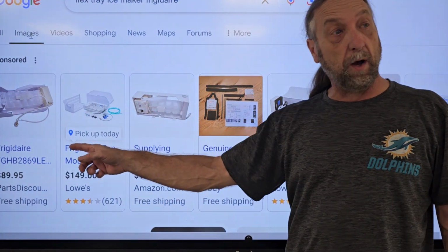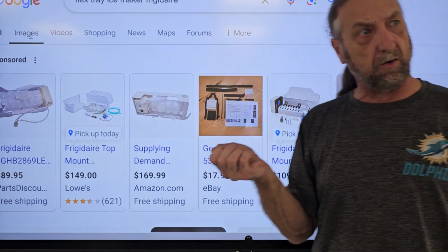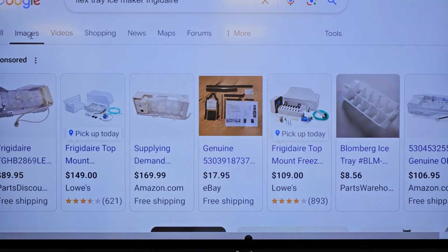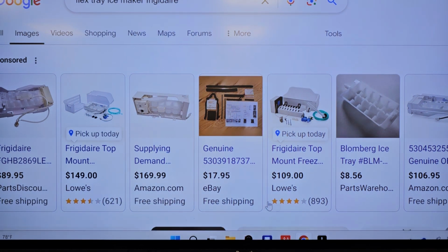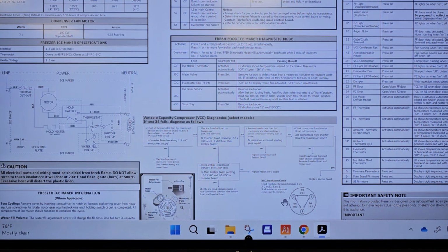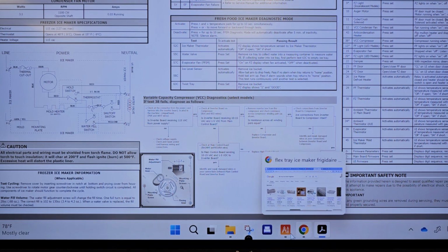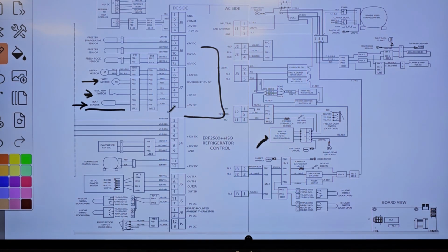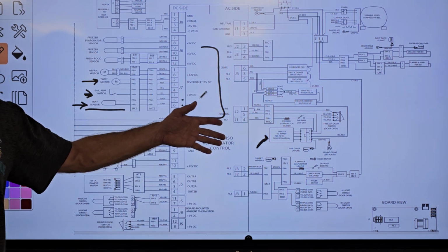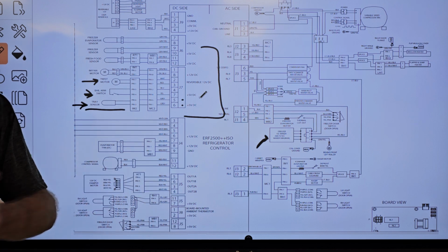But it's going to what? What is that sensor connected to? The water valve? No? Look at the diagram. The board? What is this sensor connected to? Yeah, board. The main board. The sensor's going into pin 5 and 6 on J7. J7 pins 5, 6.